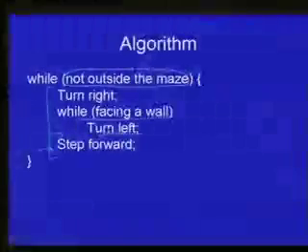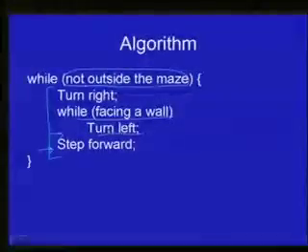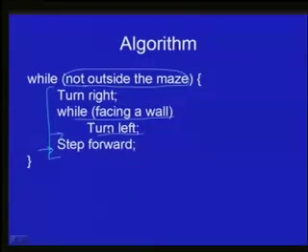So if we reach a dead end, then this loop will make sure that we turn back and come back to some place which we had visited earlier, and then later on will not go back to a path that we have already visited once. That's because when we come back to the same place, we will be facing in the reverse direction as compared to the direction in which we were facing when we visited this particular place the first time.